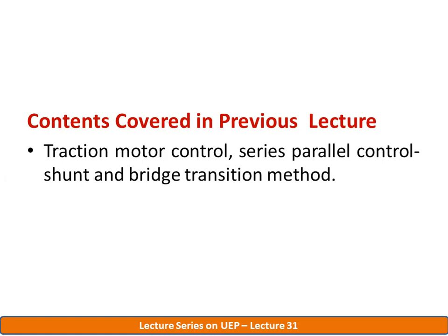When the two motors achieve the same speed, the supply voltage is equal to the back EMF produced plus the losses in the two motors. The back EMF produced is half of the supply voltage minus the IR drop of each motor.